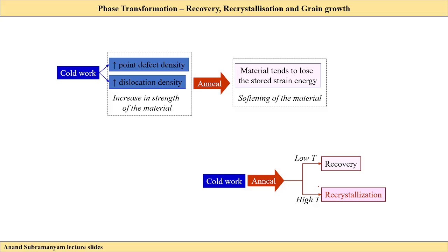So that is about the recrystallization. So that is about the recovery, recrystallization, grain growth. And in most cases people try to avoid the grain growth. Why? Because once we have a new fine grain structure, a fine grain structure is more applicable when compared to a coarse grain structure, because fine grain structure has better mechanical properties.